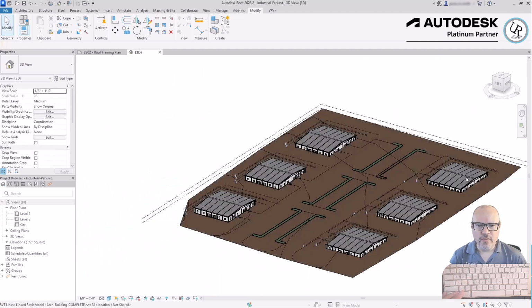and now go into a 3D view. You can see that the entire site layout has been built with all those buildings replaced and replicated from a single Revit model project. So if you're building an entire campus using the same building structure over and over again, you can lay out the site as a separate model and then link in all of the other files to it, completing that process altogether for printing or other exportation purposes.